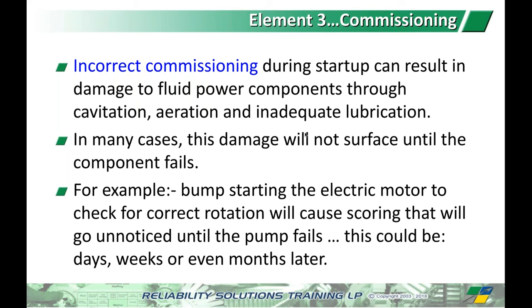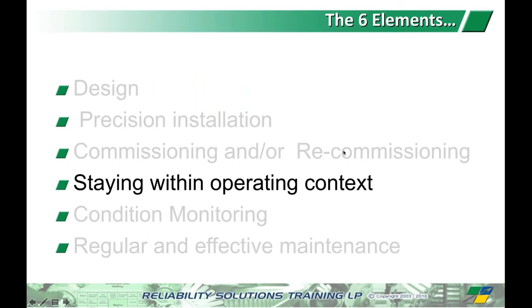and of course the other thing during commissioning that we don't do a good job of is cleaning the system after building. And making sure that the fluid conductors themselves, the pipes and tubes, are all properly cleaned out. And that just doesn't mean throw a bit of oil down them and see if they're clean. We should be sending a pig. There's a couple of companies that sell these foam pigs that will actually go out and scour the inside of the pipe and make sure it's perfectly clean to eliminate contamination. Because as we'll see later on, contamination is a big issue.